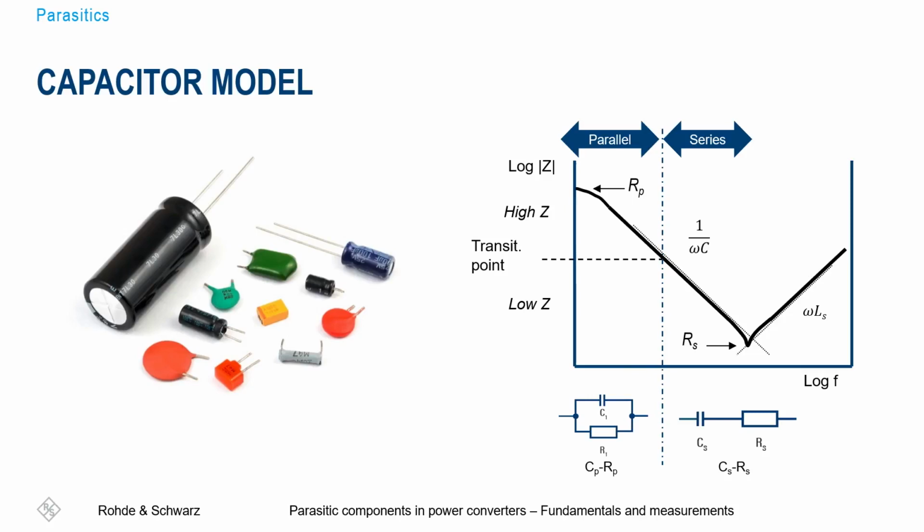For example, the manufacturers provide us the capacitance value with the ESR, or equivalent series resistance. And after this point, the impedance keeps dropping until one breaking point where the capacitor will start to exhibit an inductive behavior due to the parasitic inductance that it has. And from this point, the impedance will start to increase, and the capacitor will behave as an inductor.